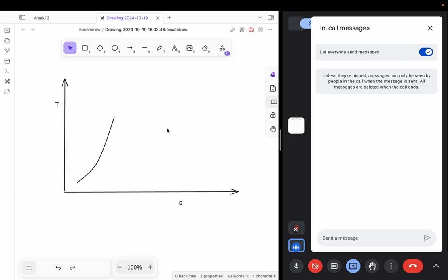It goes way higher. So similarly, you have another portion here, something like this. So the initial stage is, after throttling, you will be somewhere here, somewhere in the two-phase region, and then you will go till the saturated vapor. And once you reach the saturated vapor, you are superheating by a certain amount of temperature. So this is the first process inside the evaporator.